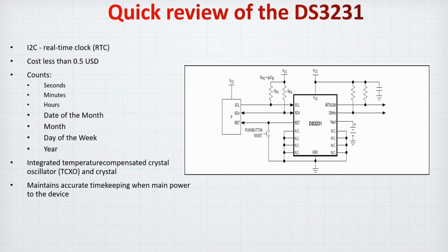Also it keeps very accurate time, because it has its own battery that you can add there, which is wonderful. Then it has a temperature sensor, so you can get the temperature data of the sensor that is used to compensate the time. You can read this data, and it has 0.25 accuracy, which is great. It's fast, with a 400 kilohertz interface, and finally it can operate from 2.3 to 5.5 volts, which is really great. So it works for the STM32F1 and also for the Arduino.